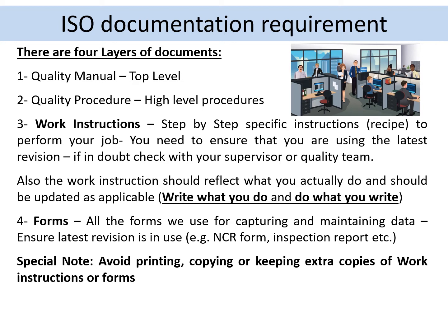On the shop floor, this is a normal practice, that we will make like 200 copies so we are good for a year. This is really a bad practice. If there is a new revision, you might not be informed, you might not know, and you may be using the old revision for months and years. So that is really a bad practice. Do not make extra photocopies, and always consult your quality team if you're using the right revision of the document.